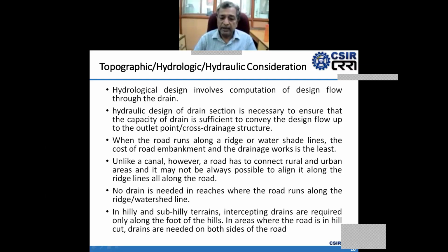In hilly and sub-hilly terrains, intercepting drains are required only along the foot of the hills. In areas where the road is in hill cut, drains are needed on both sides of the road. Later on, we will discuss in detail surface drainage and subsurface drainage.